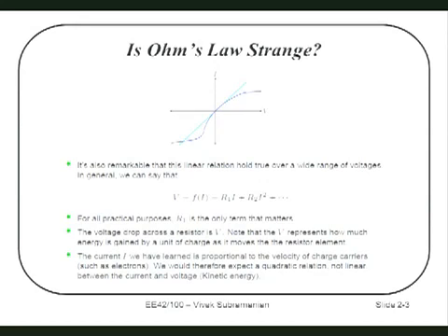Yeah? You said that current's proportional to the velocity, but in practice, when you increase current, you're not really changing the velocity of electrons, you're just changing the number of carriers? No, actually that's not true. It depends on the system. In some cases, you are changing the number of carriers. In other cases, you are changing the velocity. But in fact, the velocity only goes up linearly over a limited regime. It ultimately maxes out. Okay? But for most systems that you deal with, you're not changing the number of carriers. You are increasing the velocity, because our velocities are generally, in the scheme of things, not that high. Okay, so let's think about why that happens. Why is it linear?